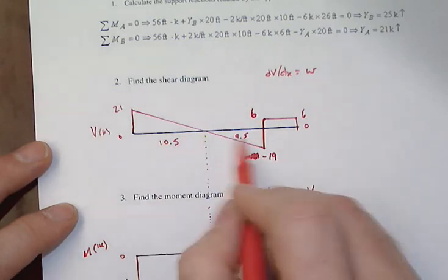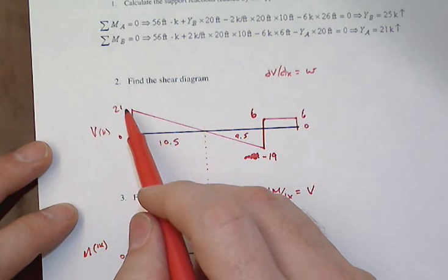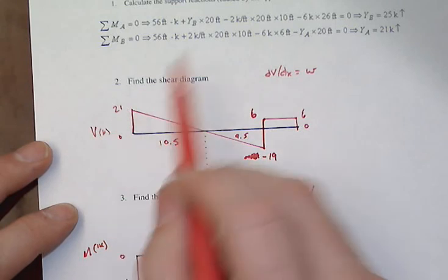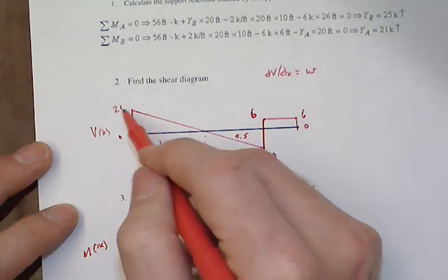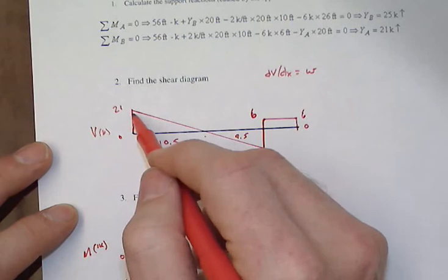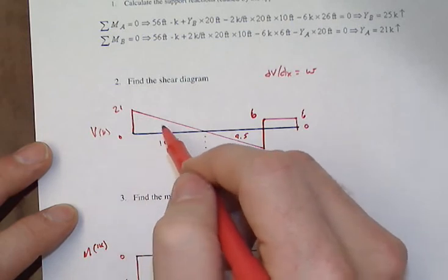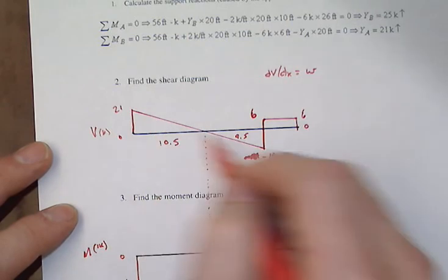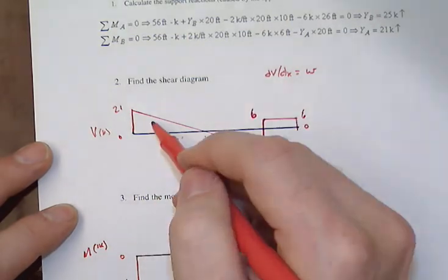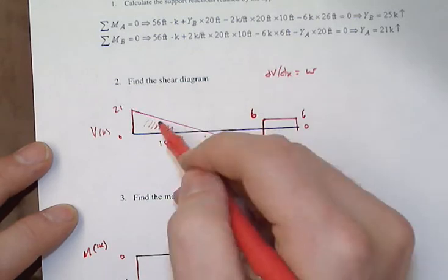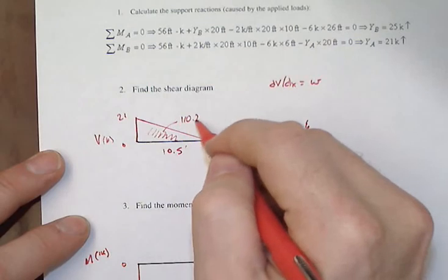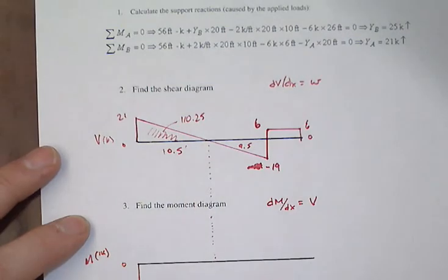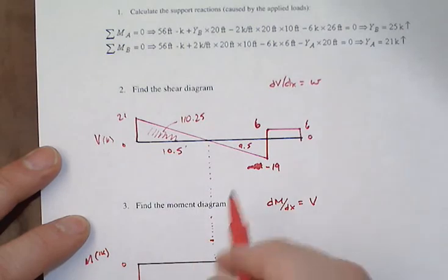I don't have to just do similar triangles to do that. Note, once again, we start off with a shear of 21 positive, and we have a negative 2 kip per foot change in the shear as we go along. So to get from 21 down to 0 at a constantly decreasing rate of 2 kip per foot is going to require 10.5 feet. In that area, that total change in the moment then is going to be given to us by the area of that triangle, and that's 110.25, 1/2 the base times the height, and that's going to leave us with a net here from minus 56 plus 110.25,